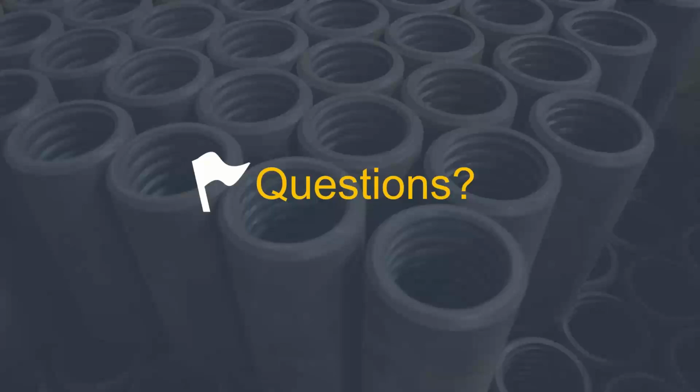You may end up in a situation where even though it's made of concrete, it is allowed to flex and not act as a rigid cap, where if you put a bending moment on it, instead of it just rotating like this and pulling up on one pile and pushing down on the other, the pile cap will actually sort of bend upward instead of transmitting that load into the piles. Does that make sense? I wish I had a better graphic.